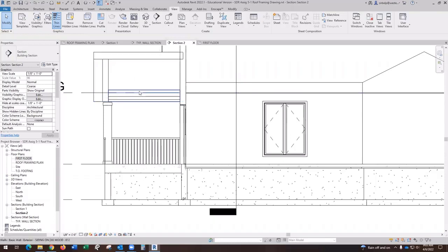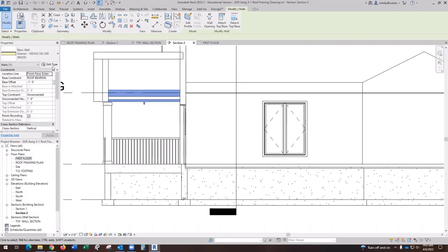So then if you look at the side one here, I didn't even bother doing what I'm telling you to do about making a beam, duplicating that wall and making it a porch beam wall, because I was in a hurry. I just used my exterior wall for my house and I drew a little beam size segment of the wall, and that made it really easy to snap my roof to it. And nobody cares because you can't see the dumb thing anyway from the outside. It was just to make my life easier.